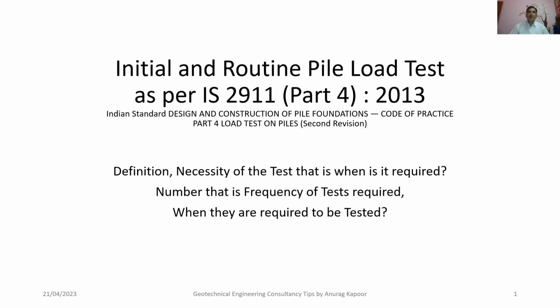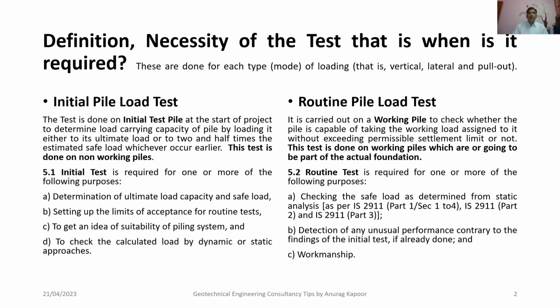Today I will be telling you all about initial and routine pile load tests, the difference in their definitions, the necessity of the tests, that is, when they are required to be done at the site, the number, that is, the frequency of tests required, and in which very particular cases they are required to be tested, as per Indian Standard Code IS 2911 Part 4, 2013, which is Design and Construction of Pile Foundations, Code of Practice, Part 4: Load Test on Piles, second revision. Now, the definition and necessity of the test, that is, when is it required.